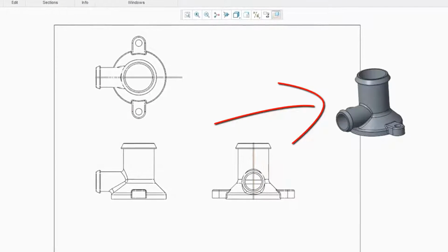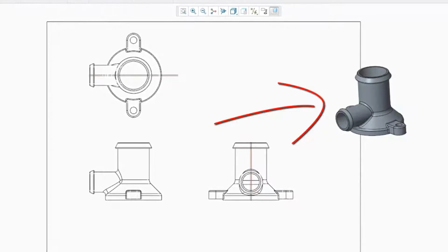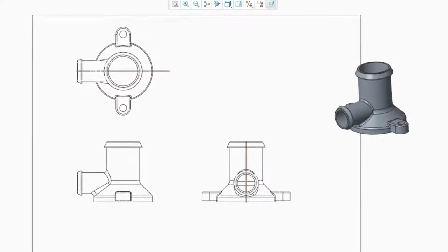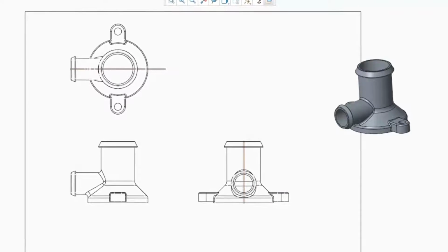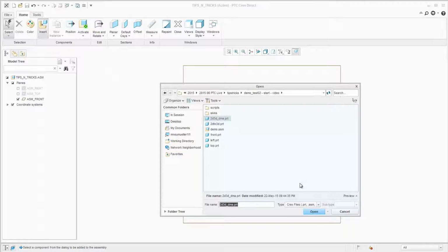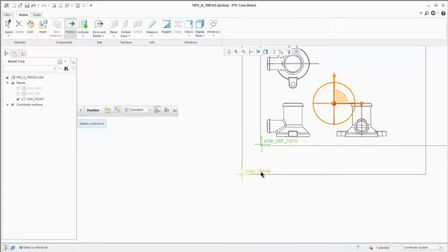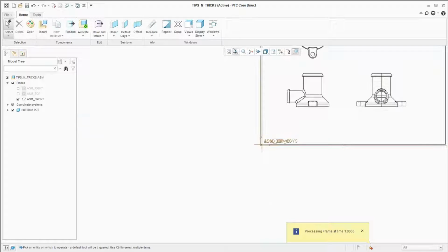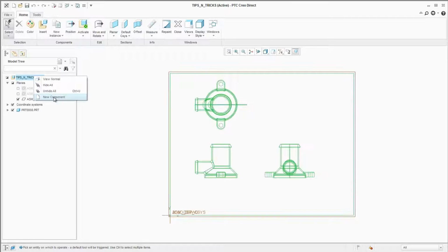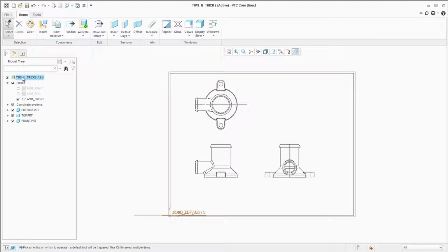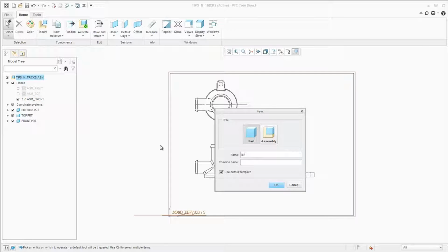As we don't have 2D drawing import into sketches functionality yet inside Creo Direct, we're going to use the IHS import as sort of a workaround to bring the 2D drawing geometry into the session. In the next steps, you're then going to see how we separate the 2D geometry for the individual views and position them relative to each other in 3D space. The approach is to quickly create new parts for each view. Then we project the view-specific drawing geometry into sketches and define coordinate systems for the subsequent placement.